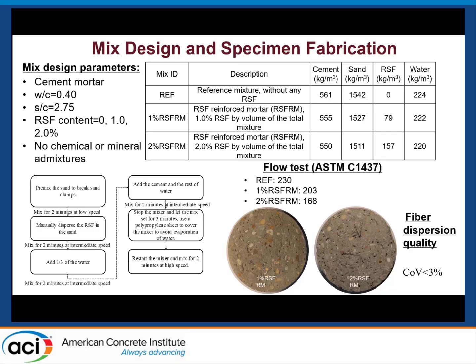Okay, so first of all, it's by volume. So 1%, 2% is by total volume of the cement mortar, the total volume of the mixture, and we did not replace sand. We just added it as an additional addition. We still use the same volume of sand, the same volume of cement, and the same volume of water.